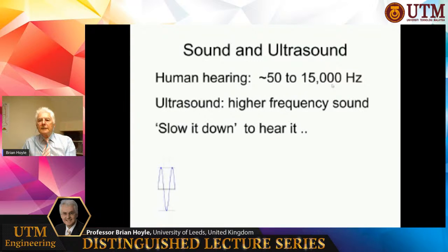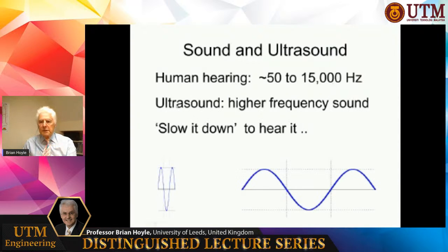So this means that our ears can't vibrate at this frequency. But what we can do, if you want to listen to ultrasound, is simply use a bit of electronics to slow down the frequency. And a little illustration then is, if this is the 50 kilohertz, say, that I definitely can't hear, I can simply record it and slow it down in time. And I can do that continuously. So I can hear it at a lower frequency.